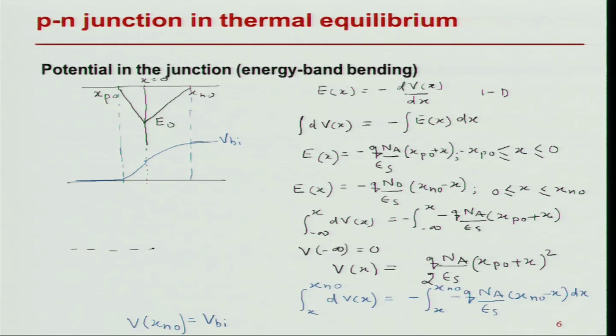In equilibrium, what I knew was that I have a Fermi level which is the same in both directions. Here, away from the junction, I have what is there in the material. In the junction now, what will happen? Built-in potential is increasing, right. Now, this potential is plotted with respect to always a positive charge, and I am plotting the energy band diagram always with respect to the electron energy. Hence, the energy band bending is always going to be, one will have to subtract that from here, and it is going to be absolutely a mirror image of the potential change.